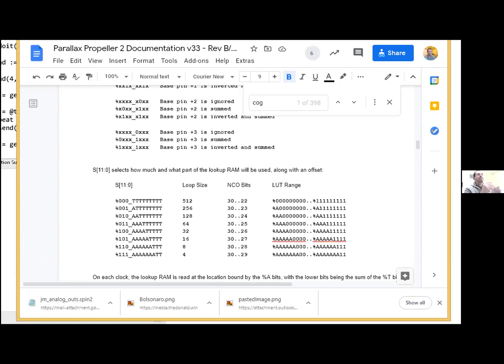Well, there is some resolution circuitry in there in case there's that kind of read on write. It'll pass what's being written. But the trouble with doing that is that you don't know what phase it's in, right? So you're going to go in with your software and write it, and you're going to hit it mid-phase and create some step function in your output waveform. That's why you'll create that step or jitter in your noise. Yeah.